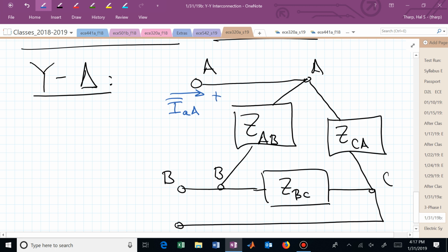Do you see that it's just the voltage between the A terminal and the B terminal? That's now V sub AB with those subscripts capitalized. And the current is in fact this current, which is I sub AB going through the impedance in the A phase of that load.